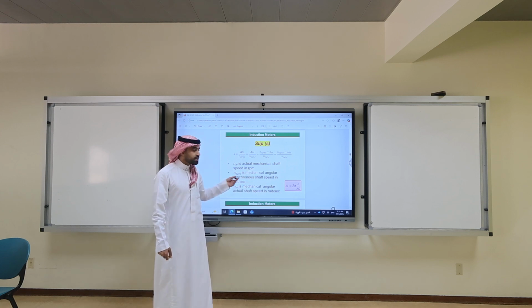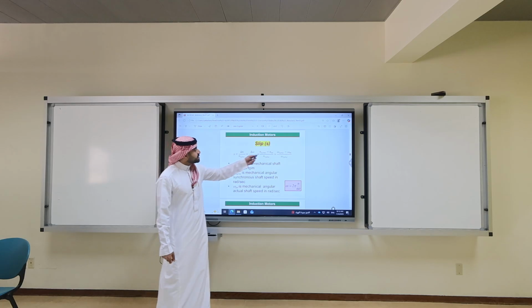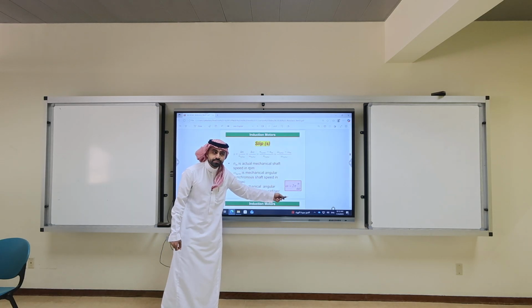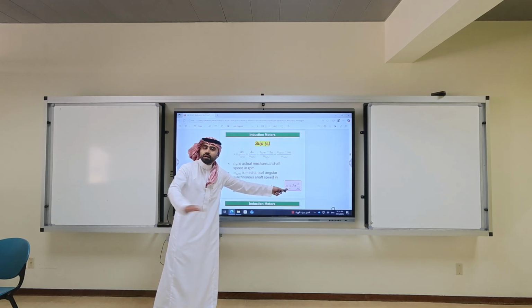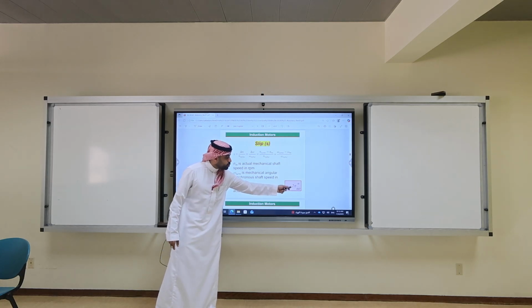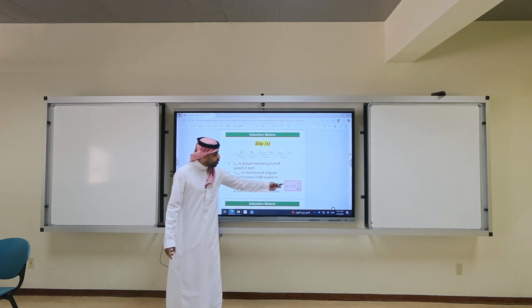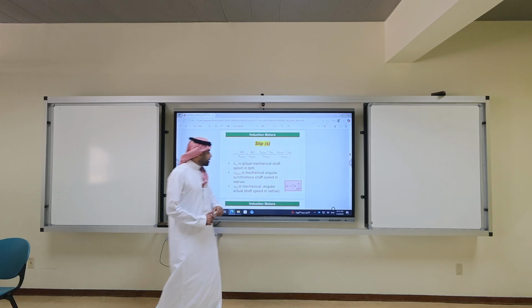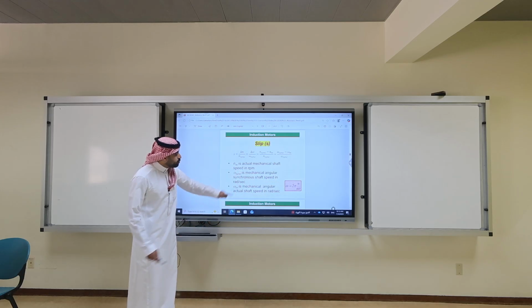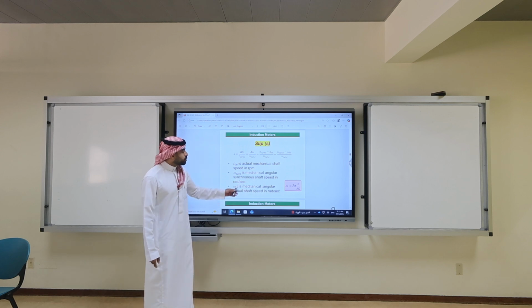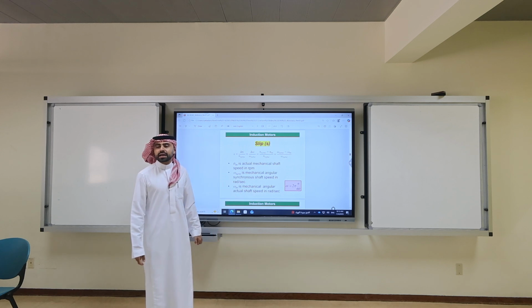Omega sync is the mechanical, angular, synchronous shaft speed in radians per second. It is the same as n sync, but you use this formula. Get it? Yes. This formula is applicable globally. Omega m equals pi nm over 60, or omega sync equals pi over 60 times n sync. Both of them have to be the same quantity. You cannot have omega sync and nm. The last component is omega m, which is the same as nm: the mechanical, angular, actual shaft speed in radians per second.